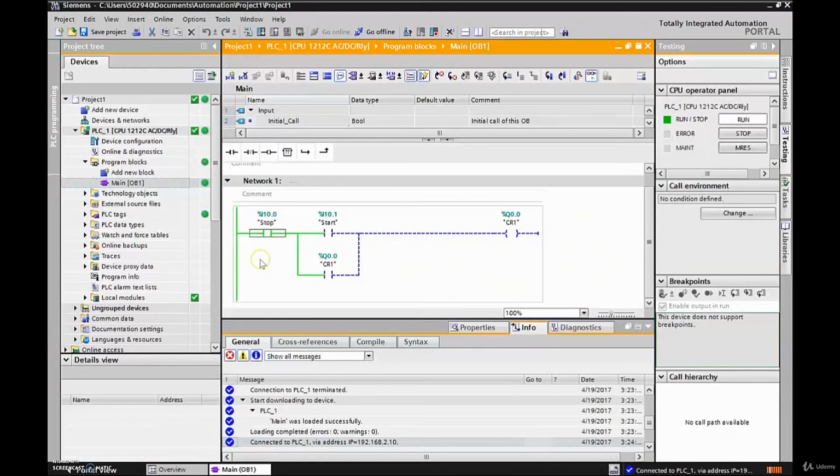on the screen here. And then all I need to do is now close my start push button, and that will turn on my control relay. Oh, very nice. Okay, and my output just turned on. Now I'm going to open up my start push button, but I should have another path of logic down here. Very cool.